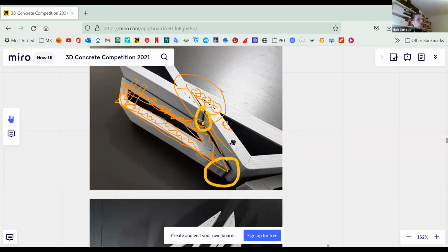all the time, for all the teams that want to put some wood on top, you need something in between concrete and wood. The concrete is all the time wet. If the wood is all the time wet, there will be problems. You need some other material, either some thin layer of water resistant material. Maybe if you put something that looks similar to wood, but it's actually not wood, maybe then you don't need it, of course.